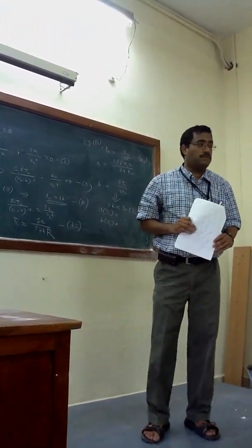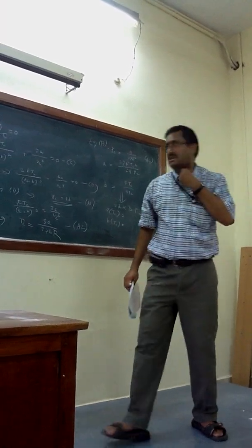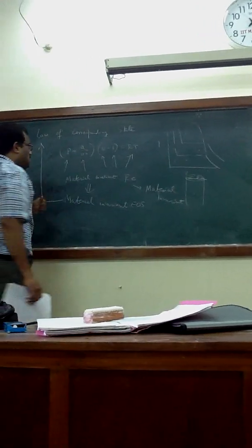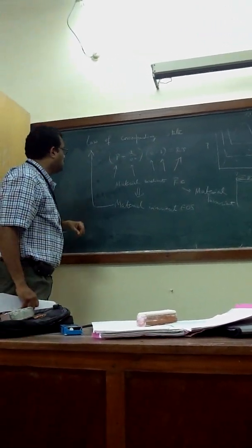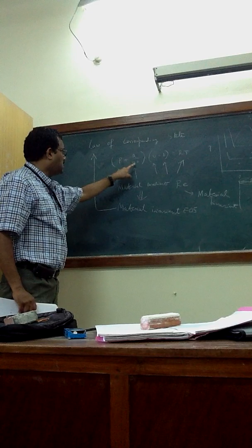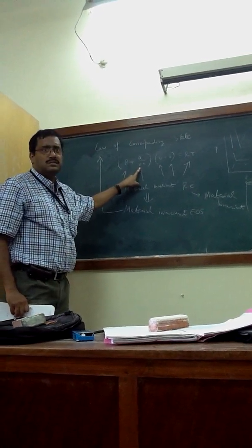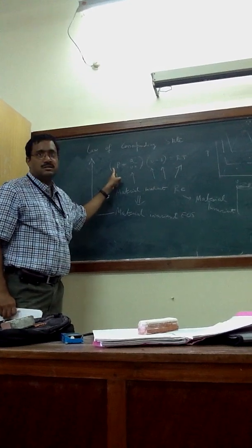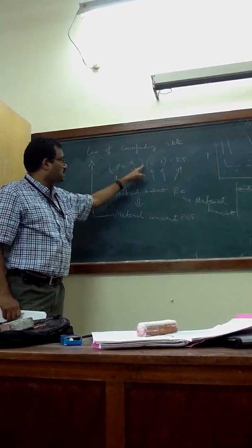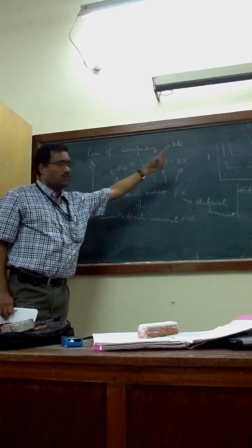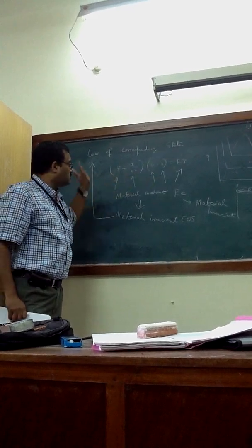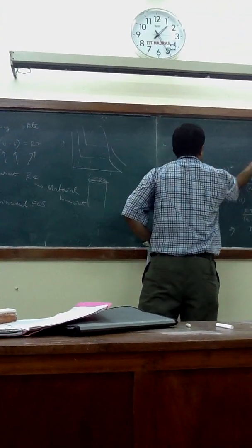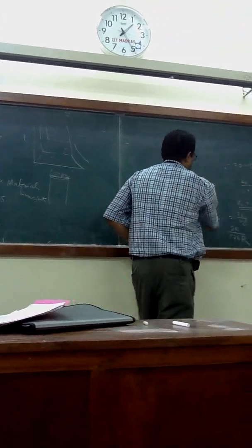What is the reduced pressure and temperature? Pc. Okay. The philosophy of this, why we do that: everything has some unit, so this has no unit, dimensionless. We have to make this dimensionless, and automatically we can get material invariant properties, which thermodynamics people call laws of corresponding states.